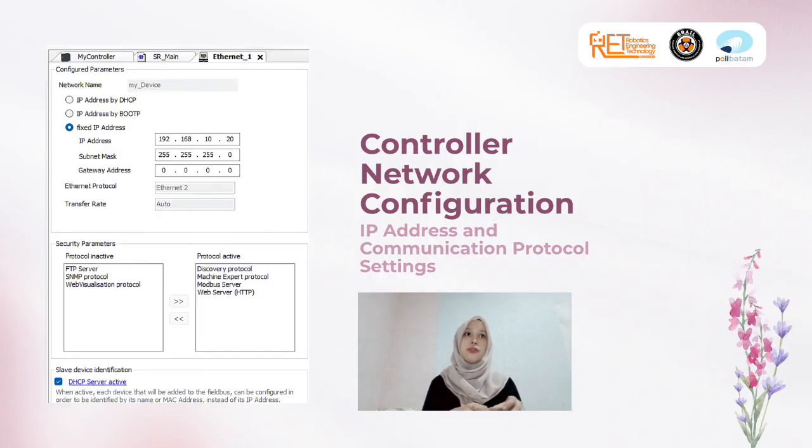I also activate the discovery protocol, machine expert protocol, and this is the important one, Modbus protocol, and the web server, which are needed so the controller can communicate with the Factory I/O over the Modbus TCP.